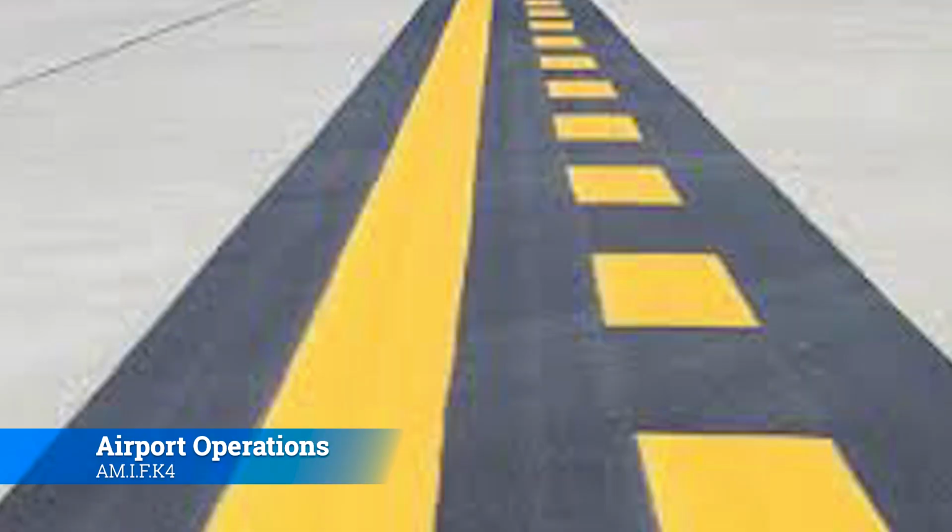You also want to pay attention to where you're at on the airport, and you're going to do that by paying attention to the lines that you drive over the top of. There's a movement line or non-movement line, which is a solid yellow line with a dash line on the other side of it.